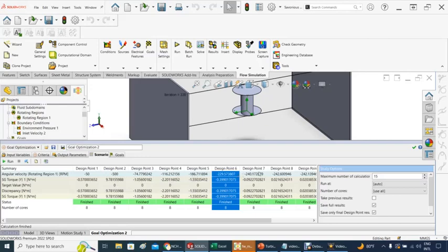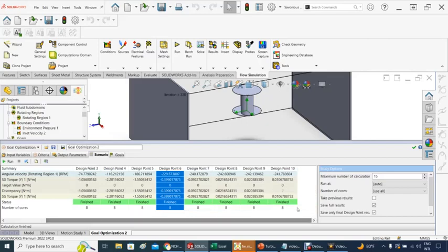Then it gets to a point, for example at 242, where it's now positive. It's almost nothing. There's no torque there at 242, but it knows that it's a positive 0.02. However, for this system, I set the plus minus to less than 0.02. So it went from here to here. And let's see what we got there. So eventually this was not good. Point number 10 was below 0.02, definitely. So this is the RPM at which this turbine will spin, where you are not extracting energy and you are not adding energy to the system. So it's about 242.